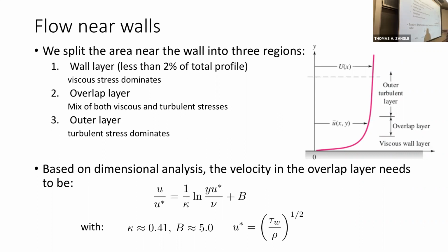And if we had a flat plate in external flow, so we have flow moving over this flat plate, that overlap layer region is going to grow and grow as we move downstream. I've exaggerated it. It would actually be millimeters to a centimeter thick for a real flow, but it will keep growing. Within a pipe, though, remember the influence of the wall grows until it meets the influence from the wall on the far side. So it stops growing at some point.